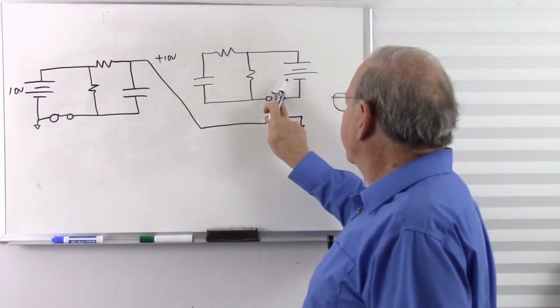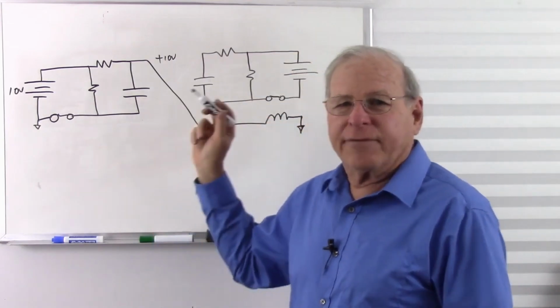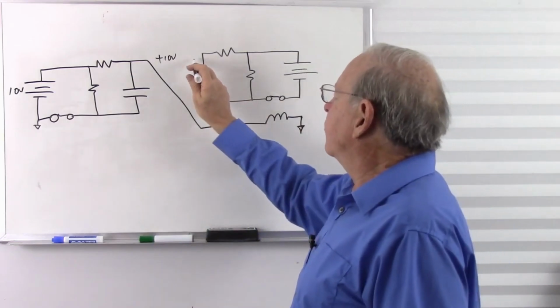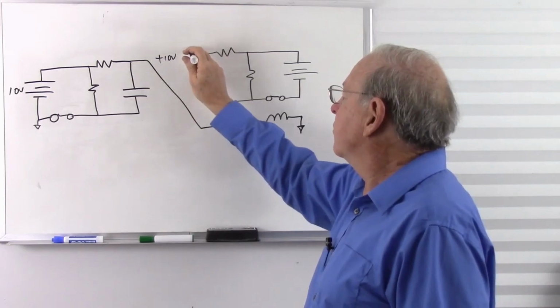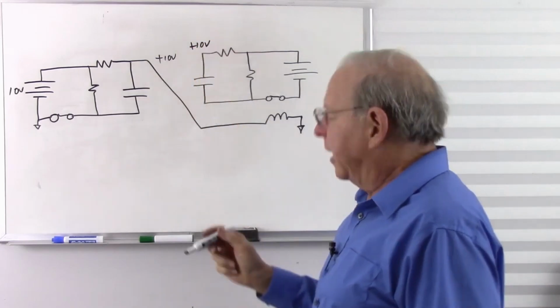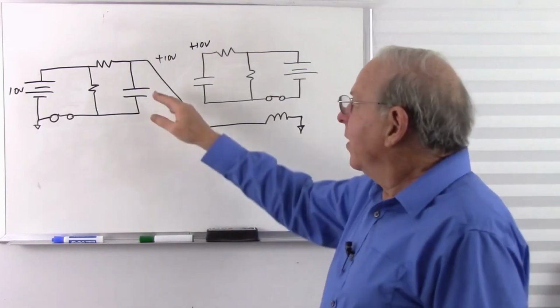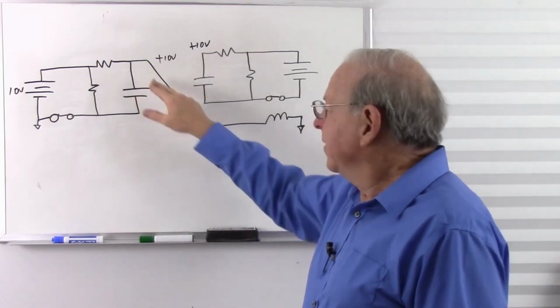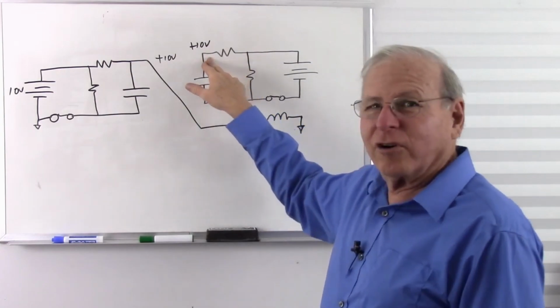And that's going to close this up. And now this is going to start charging. After 1 second, this is going to get to 6.32 volts. After 10 seconds, it's going to get to 10 volts. And charge just like that. Okay. So I got this to charge, triggered this one, and 5 seconds later, this one was charged.